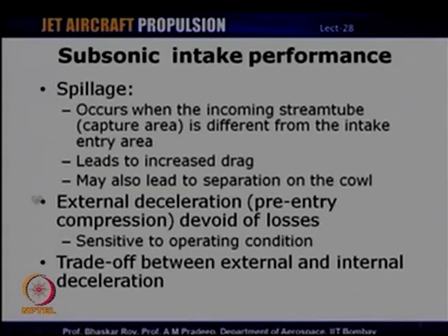Now, a designer would like to maximize external deceleration or pre-entry compression because it is devoid of any losses. But the first problem is that it is very sensitive to the operating condition, and the other issue is that external deceleration may also cause the occurrence of spillage, which reduces the overall performance of the aircraft.